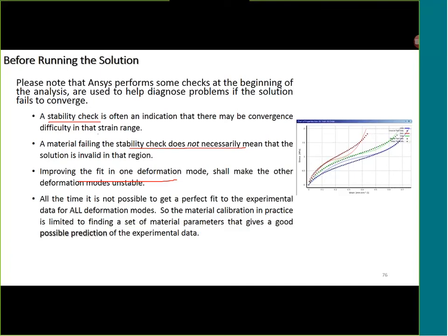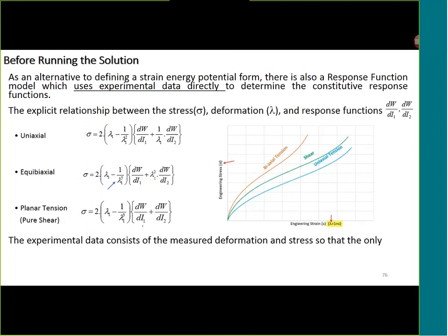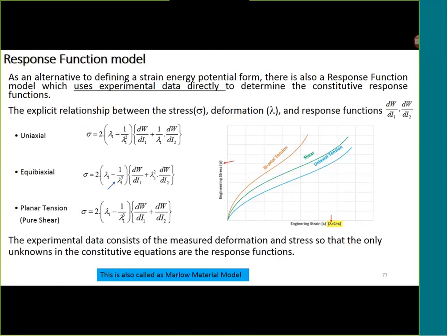So as I mentioned, it's a balance between accuracy and trade-off, and curve fitting is an art between the engineering and curve fitting with precision. Another interesting material model is the response function model. The main advantage of the response function material model is that you don't need to use curve fitting at all. It will straight away use your stress strain curve to track the response of your material.